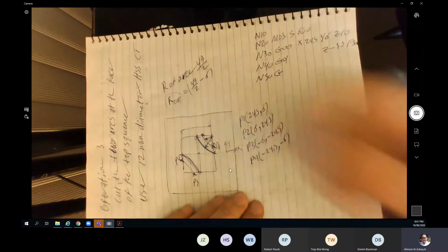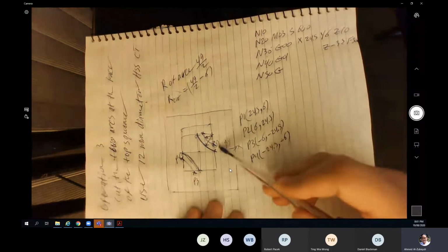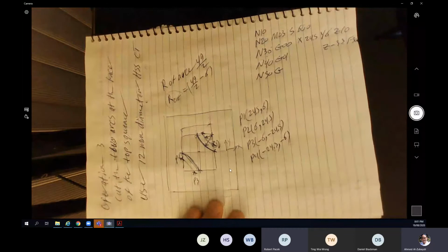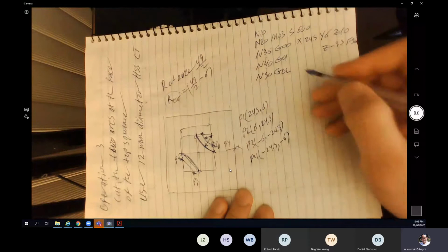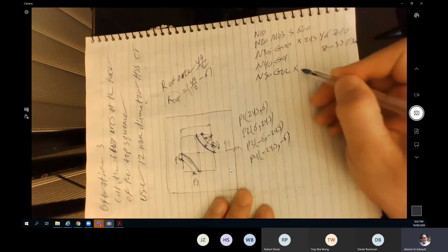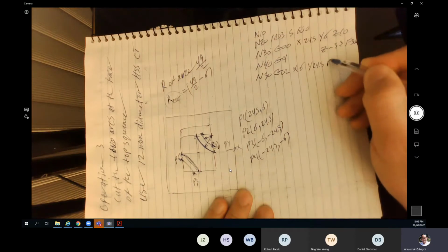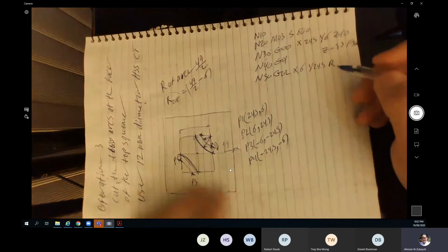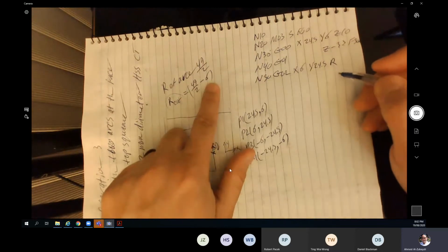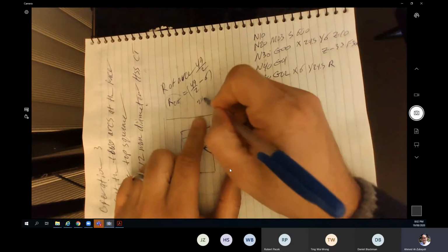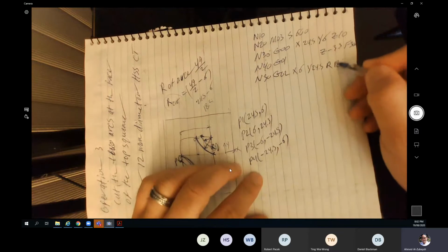Now, if we are going to move in this direction, is that going to be clockwise or counterclockwise? From 1 to 2. G02, yeah. G02. So G02, and we have to define the X and the Y of the next point. The X is going to be equal to 6, the Y is 24.5, and the R is going to be equal to the radius of this one, which is 24.5 minus 6, which is equal to 18.5. So the R is 18.5.